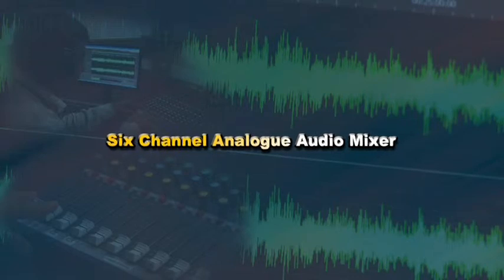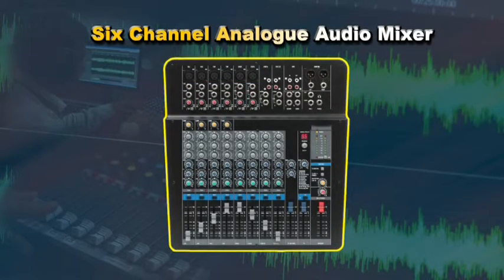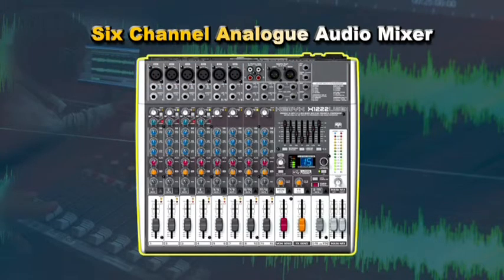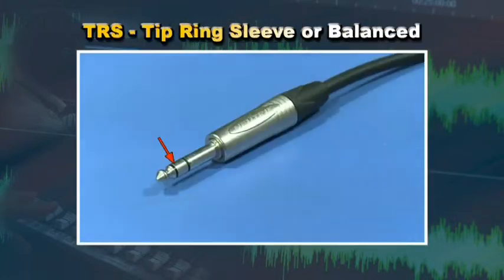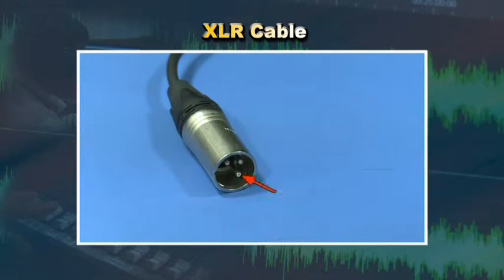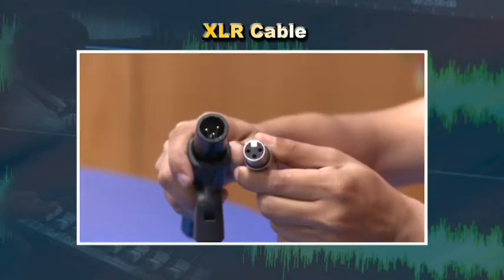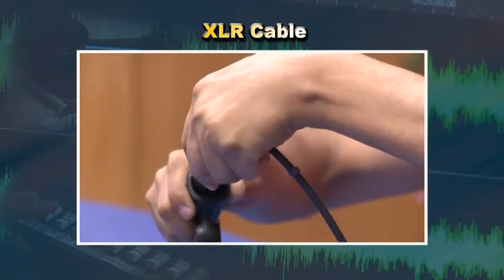Now let us discuss a simple 6-channel analog audio mixer. This particular mixer will have 6 inputs and 2 outputs. Professionally, we call it a 6:2 mixing console. The inputs will usually be XLR, TRS (tip ring sleeve) or balanced, and TS (tip sleeve) or unbalanced. The outputs are also 3-pin XLR type connectors. The outputs are XLR male connectors having 3 pins. The inputs will have XLR female connectors.